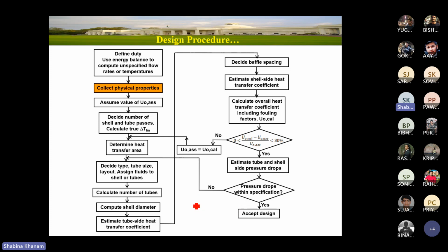Okay, viscosity value. I'm sorry that I'm not able to draw the straight line, but I think you can understand that you need to match this 60 and this point where we have located the value, and wherever this straight line cuts the right scale, that we consider as the viscosity of the liquid. So in that way you will collect the viscosity, which is one of the physical properties.